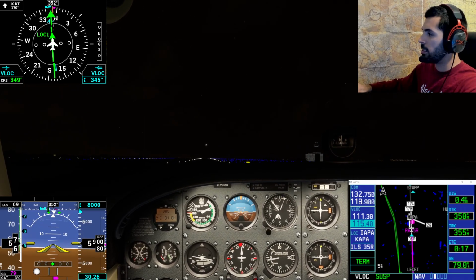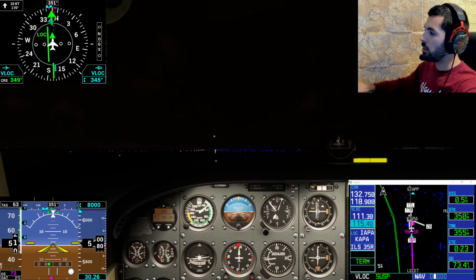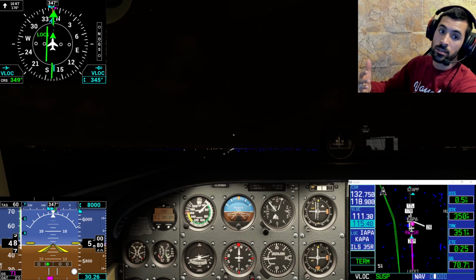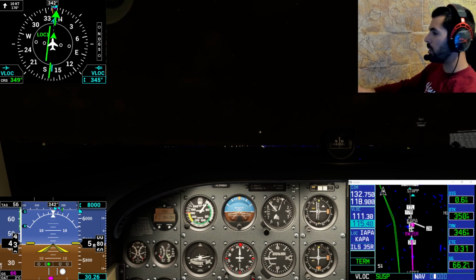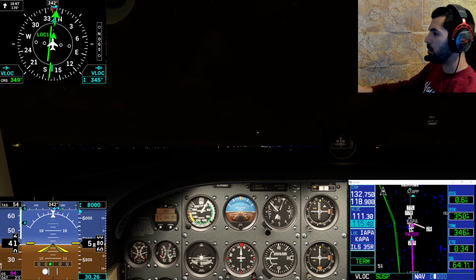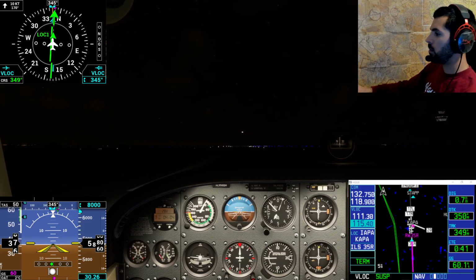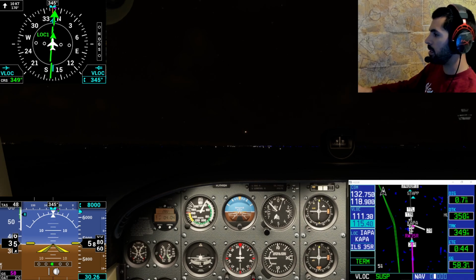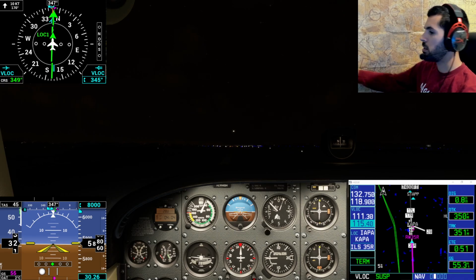And I don't have any rudder control, so I'm going to basically go off the runway. If I had rudder control, it's a lot easier to keep center line, and I think I'm going to invest in that fairly soon. But I'm on the ground, I'm on the runway, my airspeed is basically dead at this point, and now I can kind of pick up my flaps.